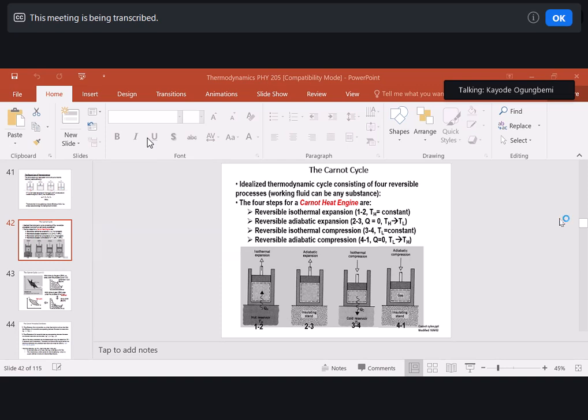And because you have given them energy, they have the ability to move up and down, to collide with each other, collide with the wall of the container, and generate pressure. And this pressure will move the piston up. Moving the piston up means work is done. That is process 1 to 2.